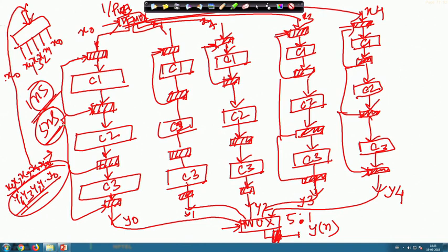So the clock period of each of these registers is 5 nanosecond. At that time you see, within 3 nanosecond I have completed the job over here, but for the remaining 2 nanosecond this block remains idle. At the C2 block I need 5 nanosecond for computation in each case.